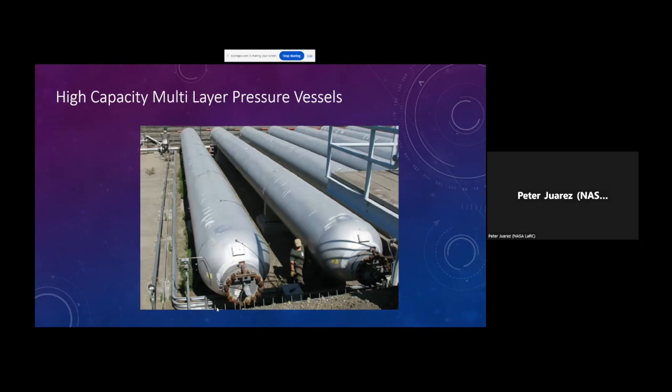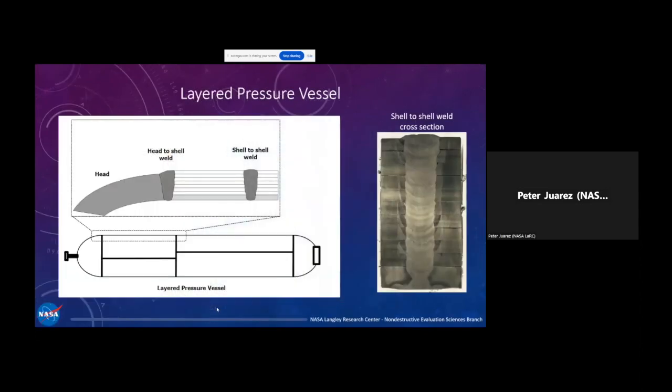Unfortunately, because they were built so long ago, they were built before the standard existed to make these types of pressure vessels, and so they were built with a design mentality of, if we over-engineer it, it'll be safe enough, which works for a long time. But unfortunately, we need to certify that we can continue to use these with some sort of analysis and inspection regime to make sure that these are in fact safe to use this late after they've been manufactured.